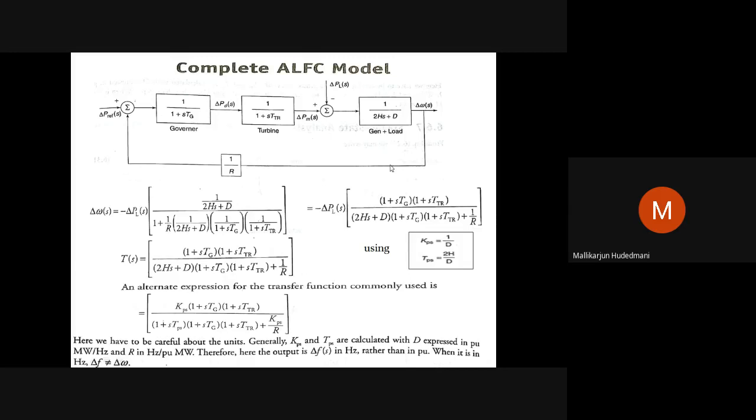This 0.1 error is fed back. What is the power actual? 1 pu. 1 pu, and this error is taken as stimulus to the governor. Governor will make the valve open. When the valve is open in proportion to the error here, definitely additional input to the turbine makes the mechanical supplement delta PM increase. Delta PM increases because of delta PV noticed.